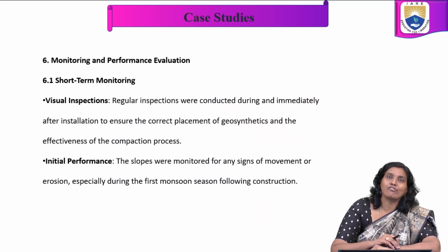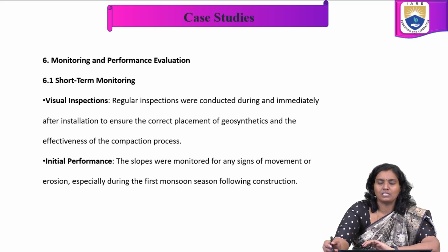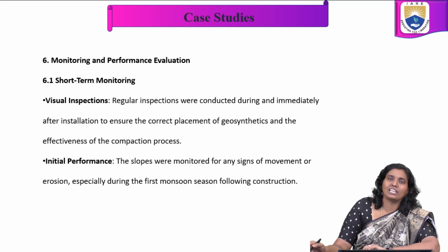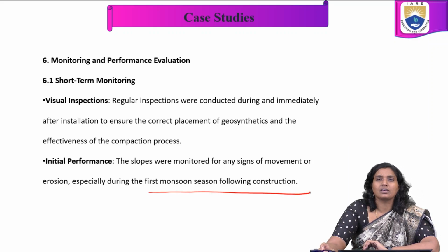In monitoring and performance evaluation, in short-term monitoring: visual inspection and initial performance. In short-term monitoring, regular visual inspections were conducted during and immediately after installation to ensure correct placement of geosynthetics and the effectiveness of the compaction process. In initial performance, the slopes were monitored for any signs of movement or erosion, especially during the first monsoon following construction.